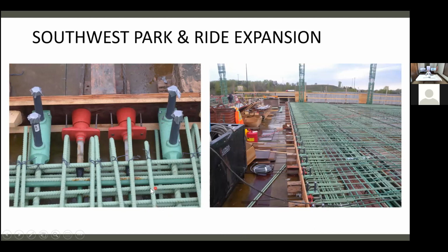So our system was more economical here. They decided they already had all these rebar bought, so they left them in place, but you don't need all that rebar. This rebar is needed because of Appendix D, now Chapter 17, for shear, not for anything transfer. We see cracks when these systems are used, where that shear bolt would do some kind of pullout. It's a non-ductile failure.